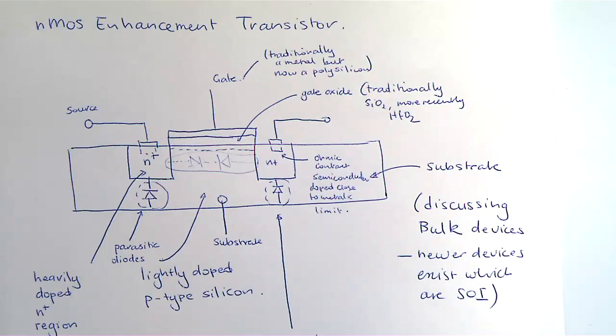You put a mask on top, and I won't talk about generating masks, but the ions that hit the mask are removed later, while the rest go and implant. It's almost like throwing billiard balls at a surface. You throw enough in there and they actually implant in the surface, and that's the implantation process.